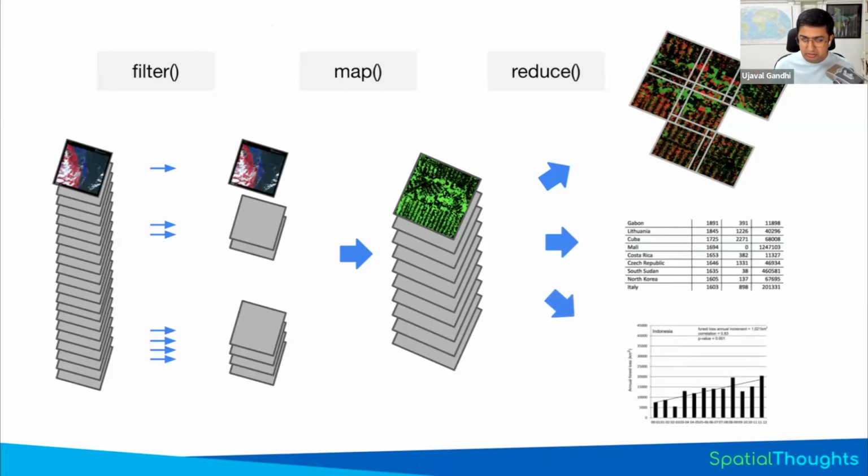So in Earth Engine, your workflow is typically, you apply some filters, you map the function to process that collection, and then you reduce the results to see the result that you want. And so now what you want to do is you say, I want to get the surface water area statistic for this polygon. You need to think about what filter would I use, what function would I map, and how would I reduce my results. Once you break down a problem into these components, programming in Earth Engine will be simpler, and you'll be able to translate your workflows into what Earth Engine needs.